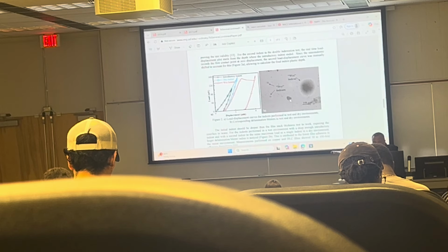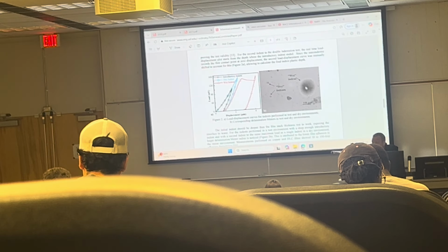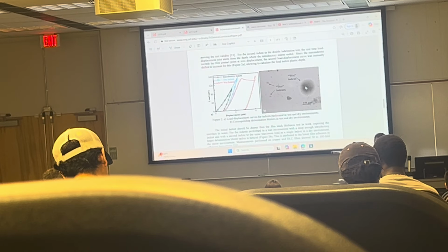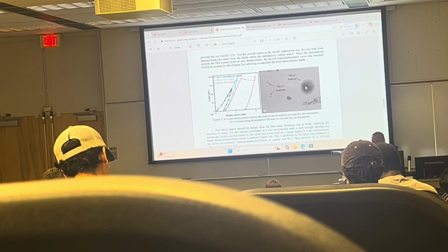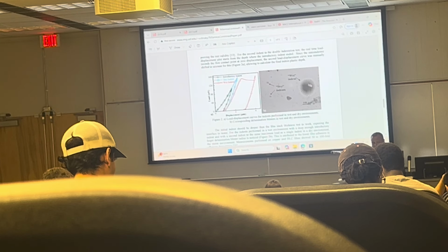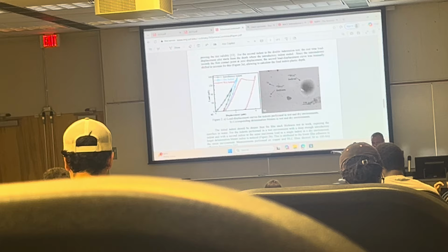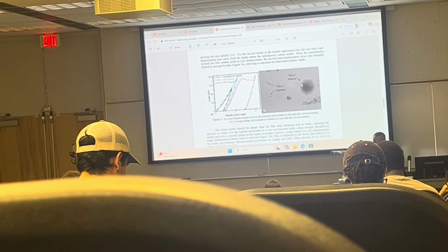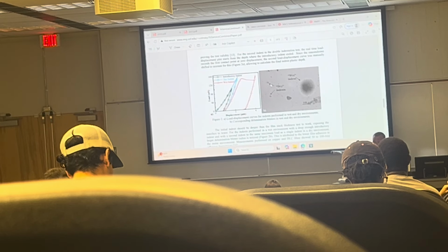And we performed this test without the presence of moisture, and this one is with the presence of moisture. So water reduces the adhesion of a thin film over coating by at least a factor of 10. So this was done with the same indent, right? And the smaller the blister, the better the adhesion. So this is the wet indent, this is the dry indent.